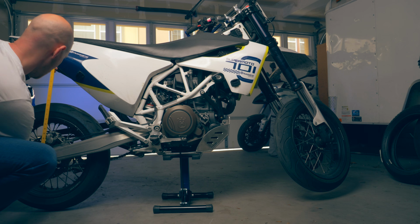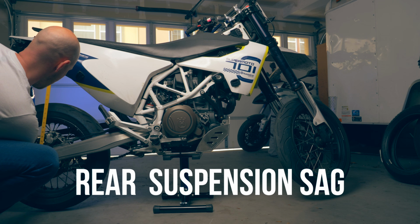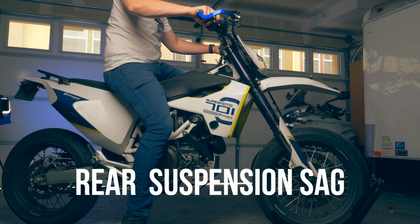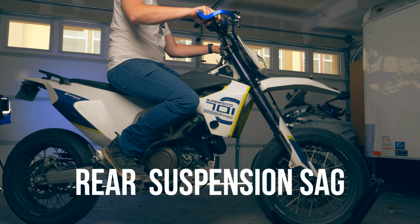I mentioned that you should measure your suspension sag. Well, how do you actually do this? Well, there are several methods, which you can read about in the books that I mentioned. For the rear suspension, you need to measure the distance between the axle and a near vertical point on the frame with the suspension fully extended, and then with the rider sitting on the bike. To fully extend the rear suspension, you need to get the rear wheel in the air.